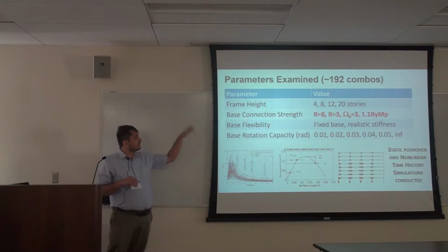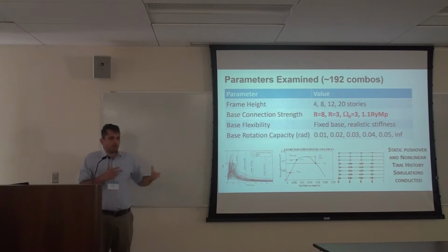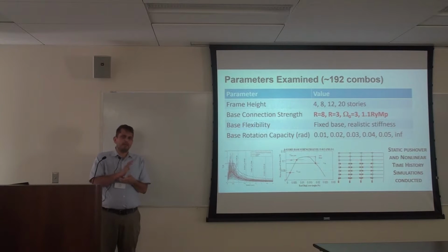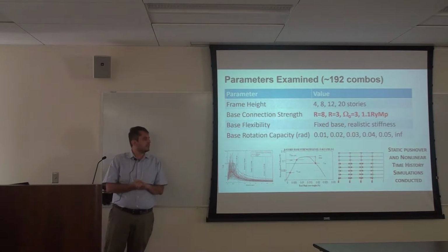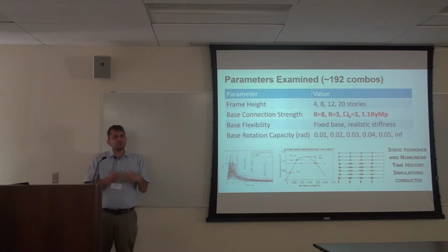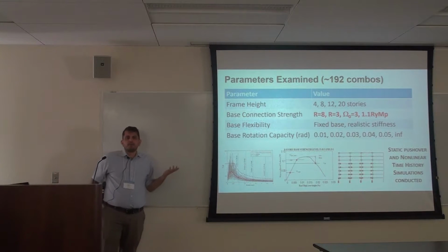We looked at 4 buildings, 4 through 20 stories. We also looked at the sensitivity to base stiffness. So we did some with fixed base. We also did some with stiffnesses that were more realistic, the expected values of column base stiffness. And then we started looking at rotation